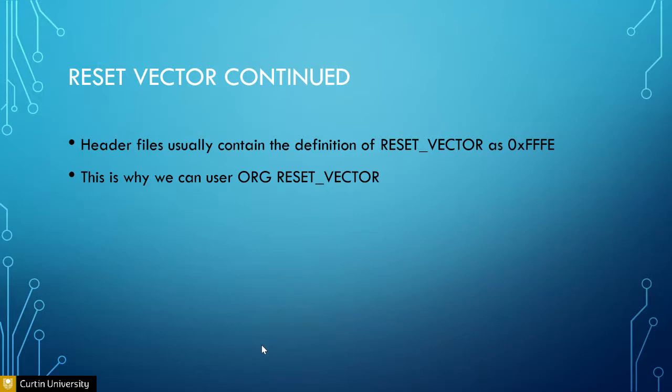Reset vector is always 0FFFE. Again, the reset vector is always defined as FFFE. So when you set the reset vector, you can go to this reset vector. This reset vector word always means FFFE, just like how bit 0, bit 1, or bit 2 have certain values associated with that reserved word. So reset vector is FFFE, reserved for this purpose.